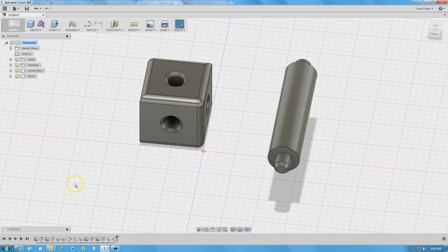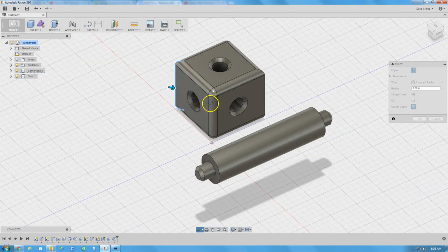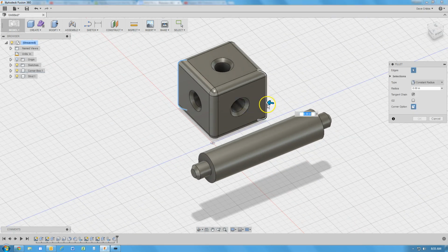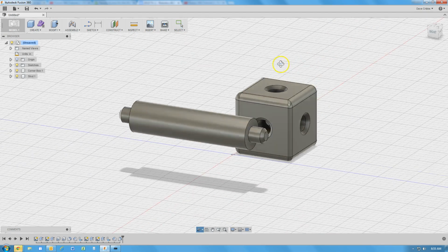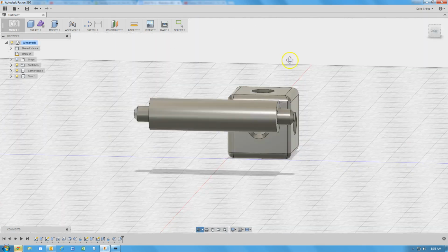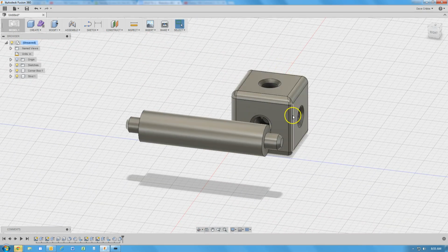So the great thing about a CAD model is I can come in here, I can click on Modify, and I can grab this edge and this edge. I can go back and I can put 0.05 and I can fix my mistake. So now I think that I've got all of the edges. And I can look and see that that edge is skinnier than those two.